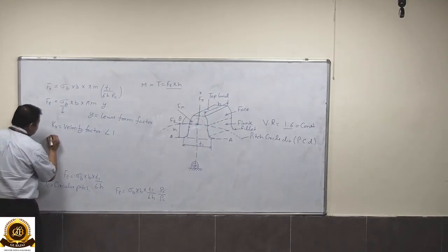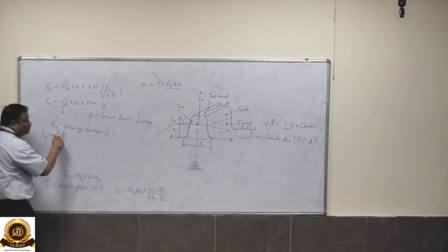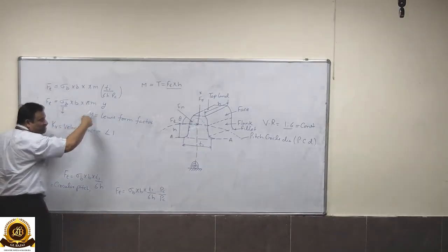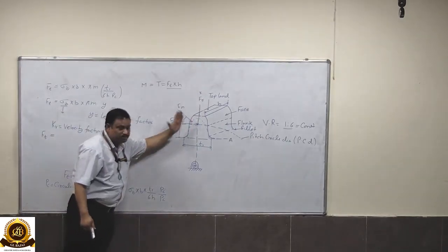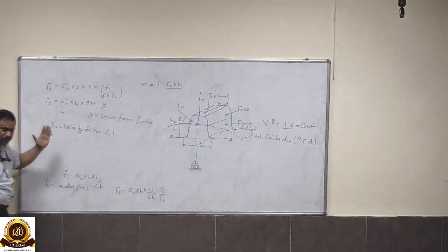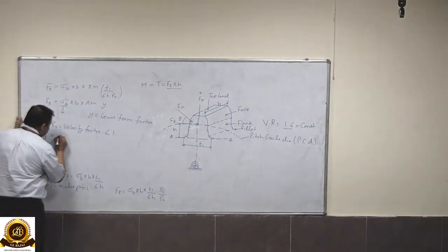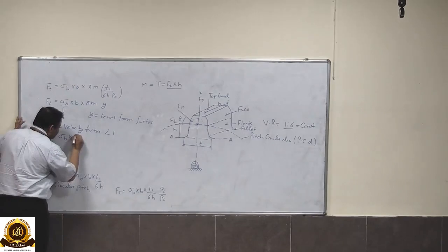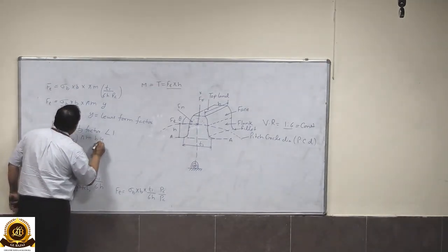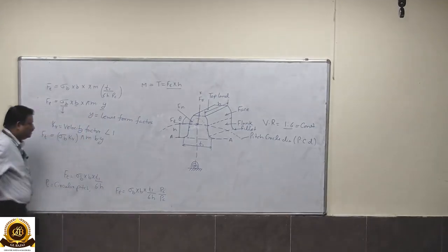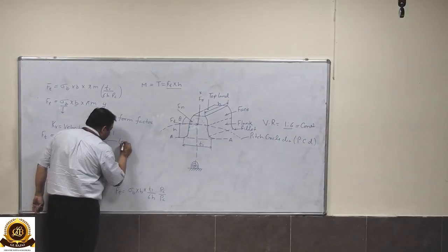So therefore we reduce the permissible stress value and then increase the dimensions of the gear to increase its strength. So this tooth should have sufficient strength against fatigue failure. Therefore this is equal to sigma b multiplied by Kv into pi into m into b into y. Now this is the Lewis equation.